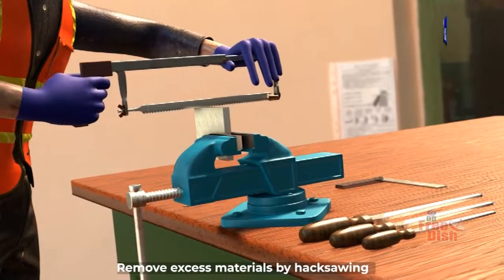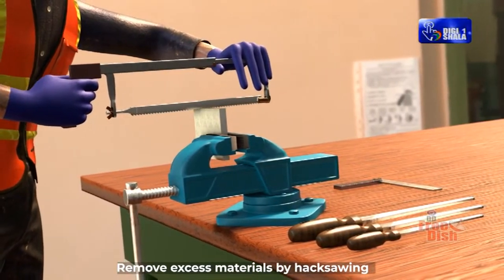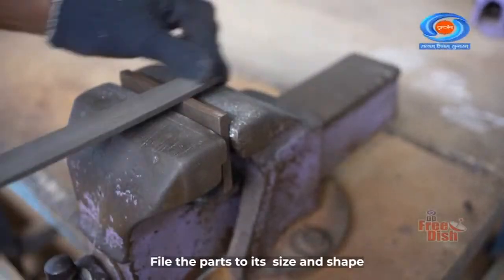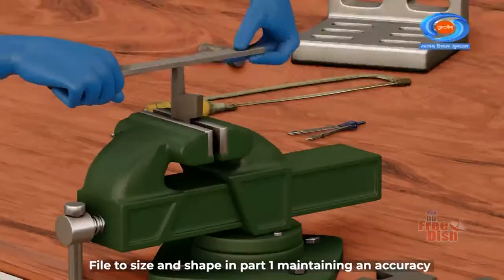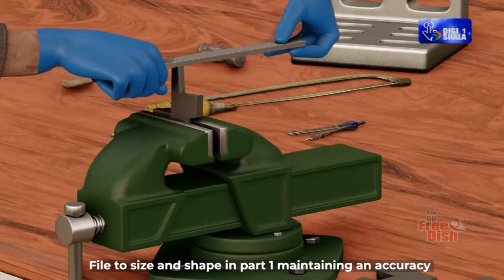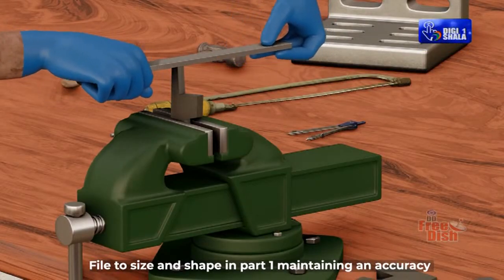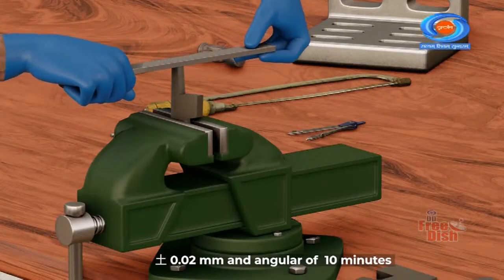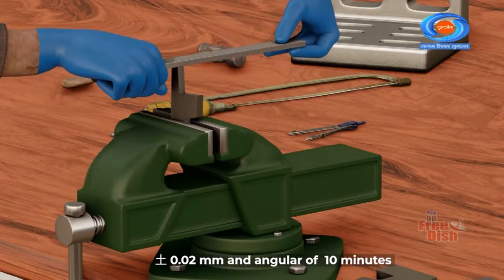Remove excess materials by hacksawing. File the parts to its size and shape. File to size and shape in part 1, maintaining an accuracy plus or minus 0.02 mm and angular of 10 minutes.